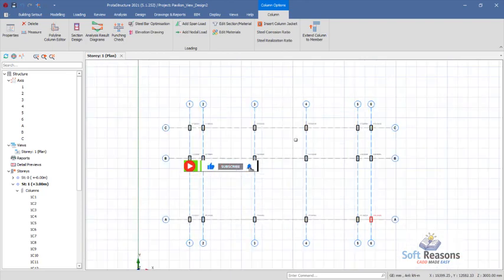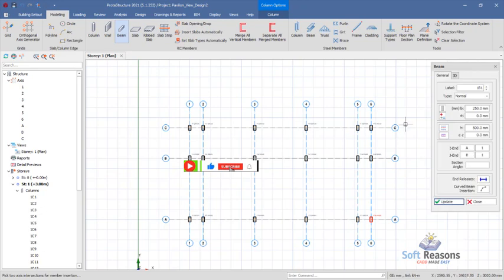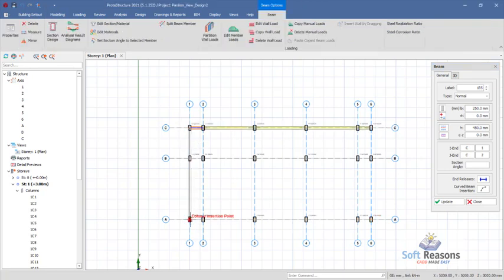We proceed to insert the reinforced concrete beam members. Come to the modeling, and then under the RC members you can see the beam member right there. Click, and then we will be having the section 250 by 450 right there, so we change here to 450 successfully. Okay, so we have our beams connecting these external columns successfully just like this.